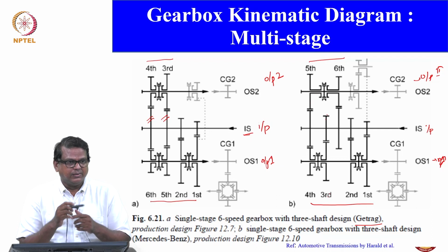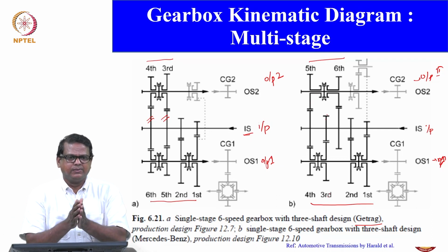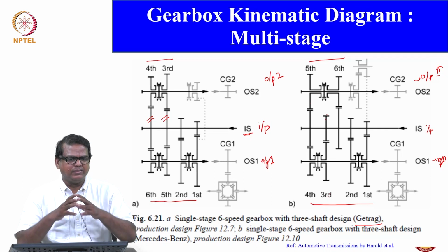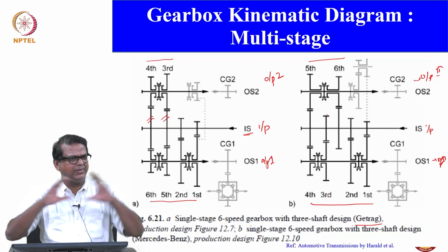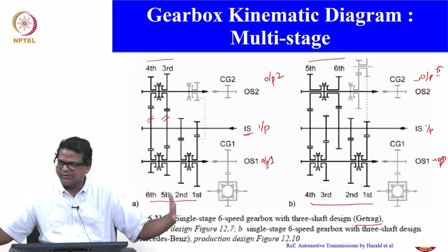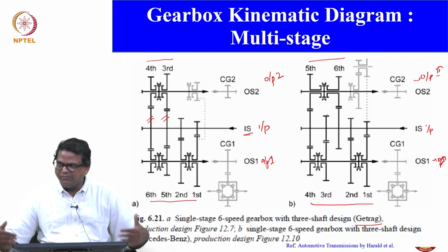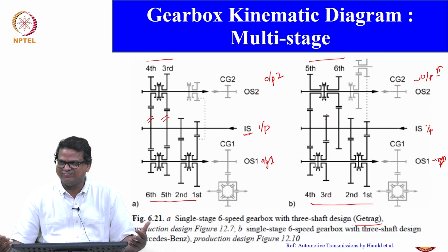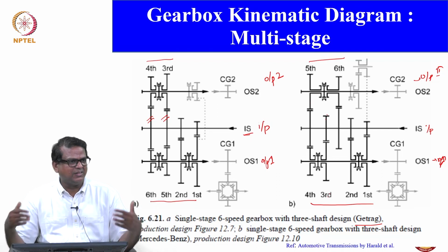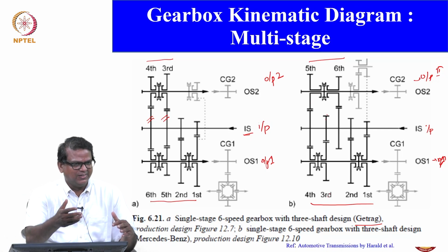In fact, what I want to say is that before designing the vehicle, they will fix the engine size, the engine dimension. So based on the engine size and dimension, we have to design the gearbox. It's not the other way around, designing the gearbox and then going for the engine size and vehicle size.